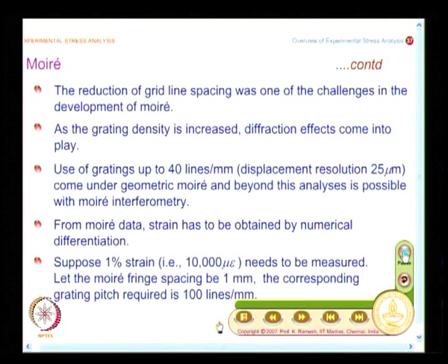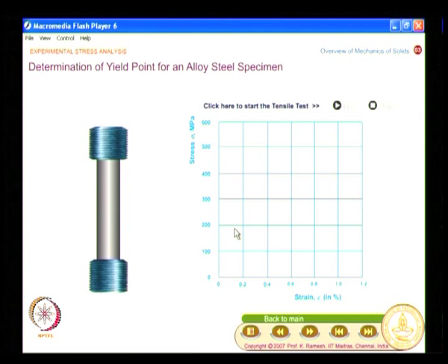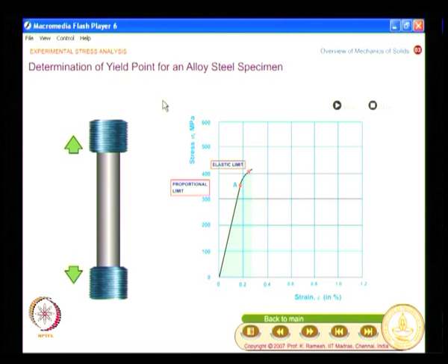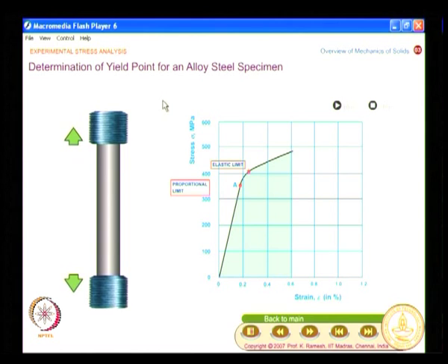And what I want to caution here is, I gave the example long time back of somebody going to a doctor and finding out whether a 105 degree temperature is small or big. He should not refer to an encyclopedia. And when you have difficulties in finding the yield point, which is not marked sharply, then you have the offset method, and you locate the yield point on the stress strain curve.